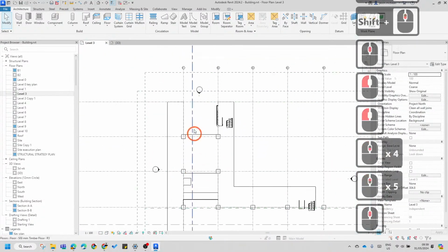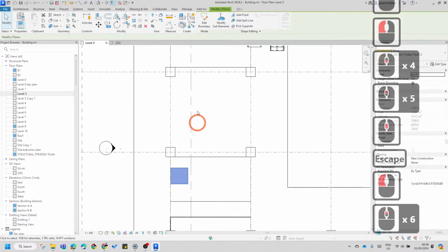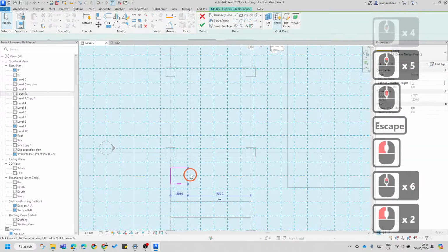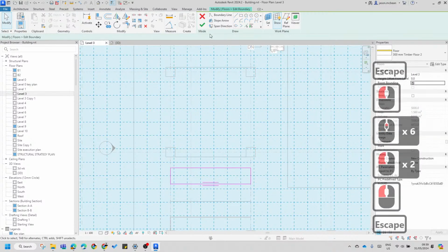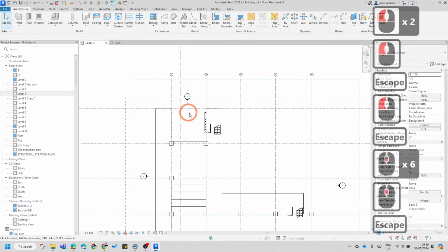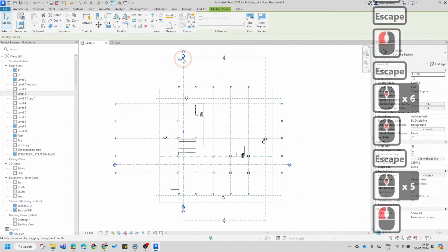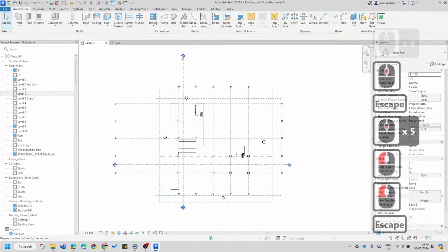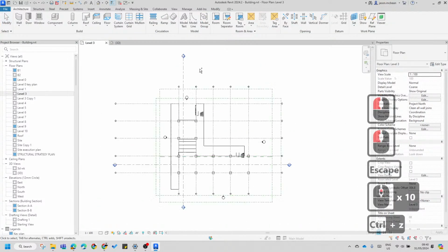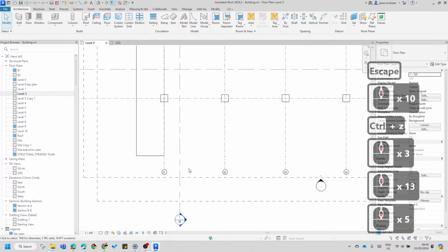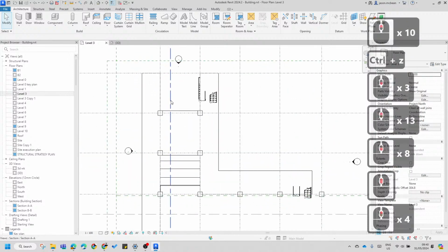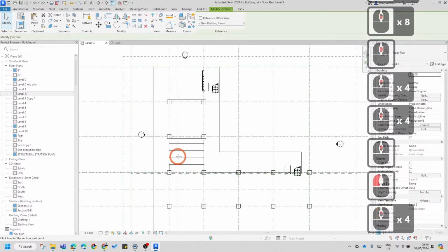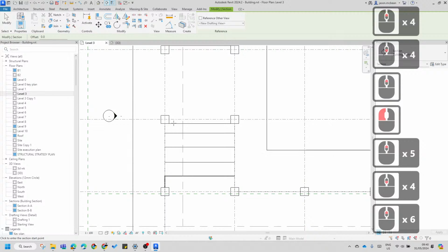Level 3. If I go to this section now, let's drag this floor and let's say edit footprint. And let's take this across. I'm going to switch it in that direction. Just be careful, because if this is on a sheet, which it is, I would then create a new section now. And this is a working section. I'll delete it straight away.